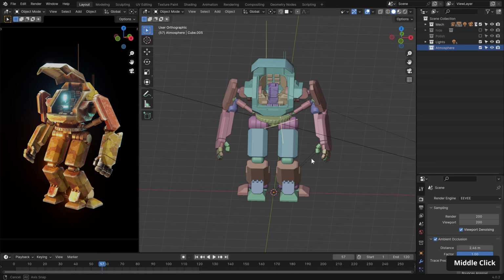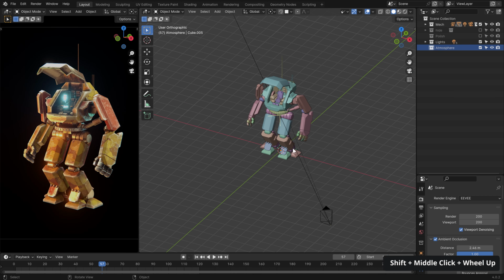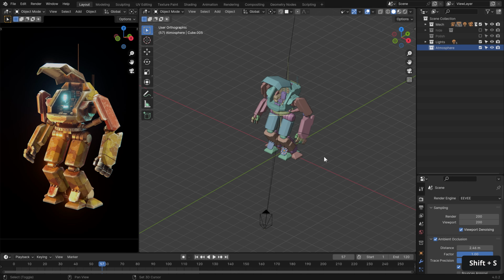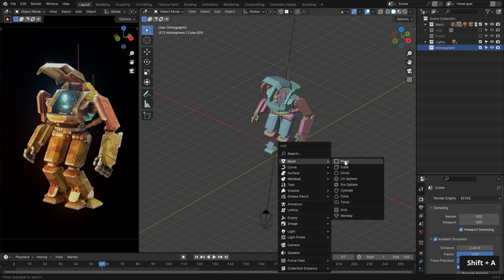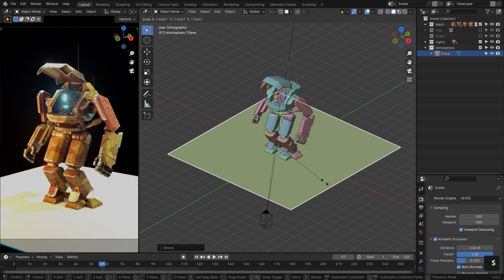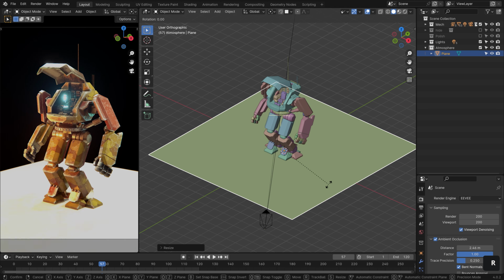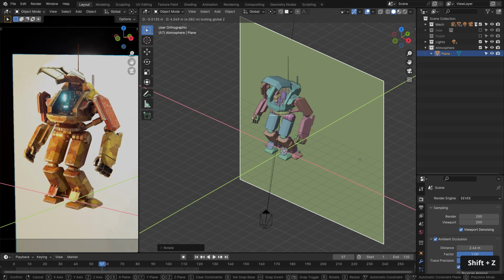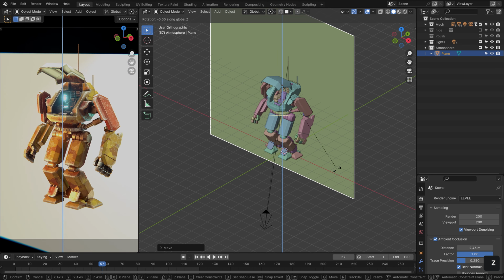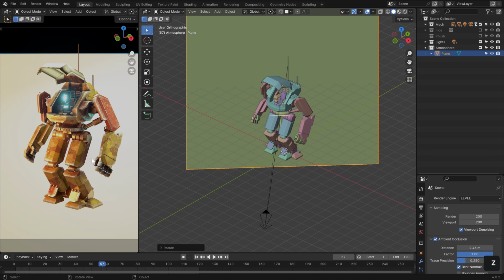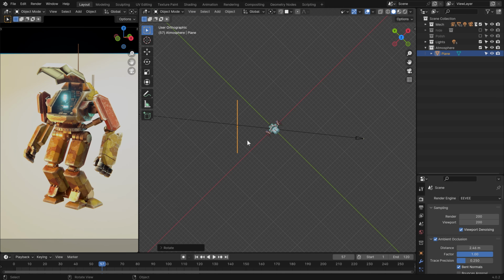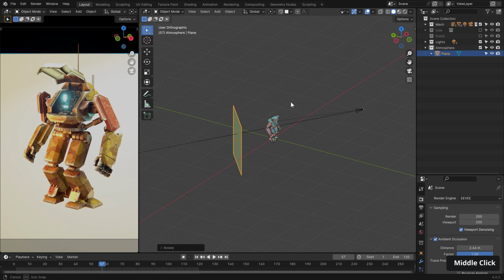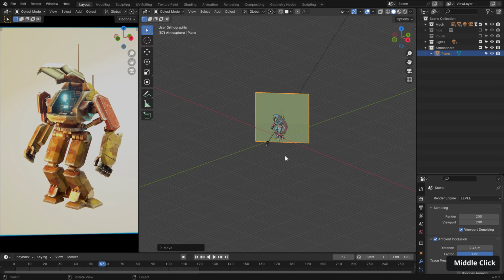Okay, let's get creating our Radial Glow backlight. First things first, let's make sure our cursor is in the world origin. So Shift S, cursor to world origin, and then Shift A, mesh, plane. Now I'm going to scale this up a considerable amount and then hit R to rotate on the X 90 degrees. And then we can hit G, move it behind a little bit, rotate it on the Z, and generally position it so it's in the background as dictated by the relationship between our camera and said object. So something like that looks good.